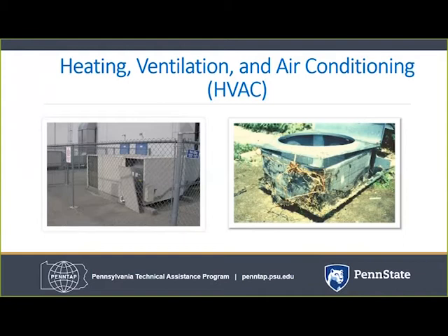Programmable thermostats can also provide significant savings. In the winter, set your thermostat to 68 degrees Fahrenheit during operating hours and to 55 at other times. As with compressed air, you want to make sure you're not losing air to leaks. Seal your heating and cooling ducts.